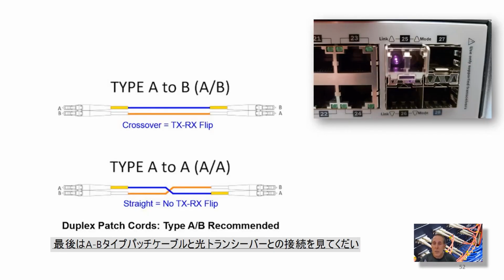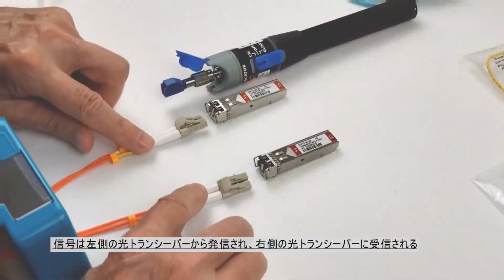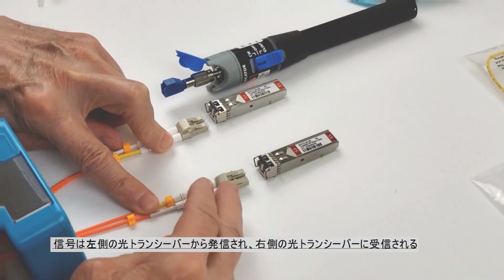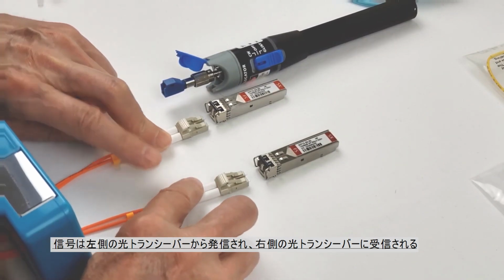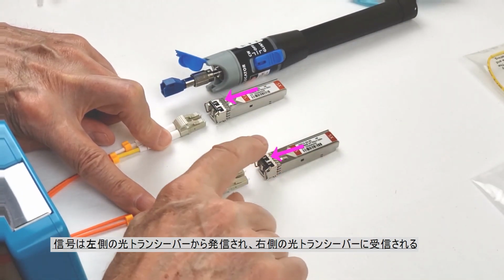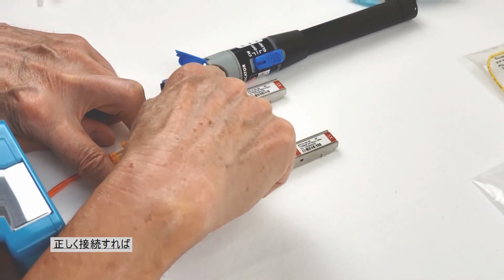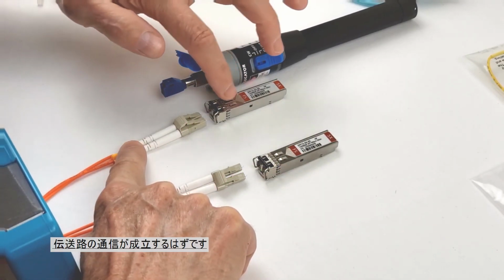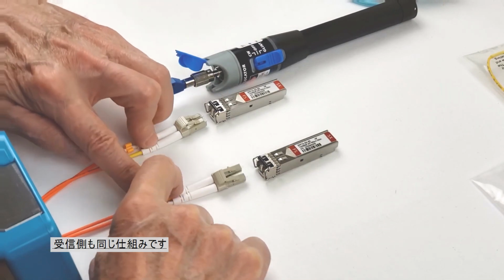Your typical duplex patch cable is going to be an AB type. So I'm going to demonstrate an AB patch cable that you would normally buy from a store. Remember, the 2 transceivers on the table have the transmit on the left side, receive on the right. So if the patch cable is right, it should automatically connect the transmit on one side to the receive on the other.